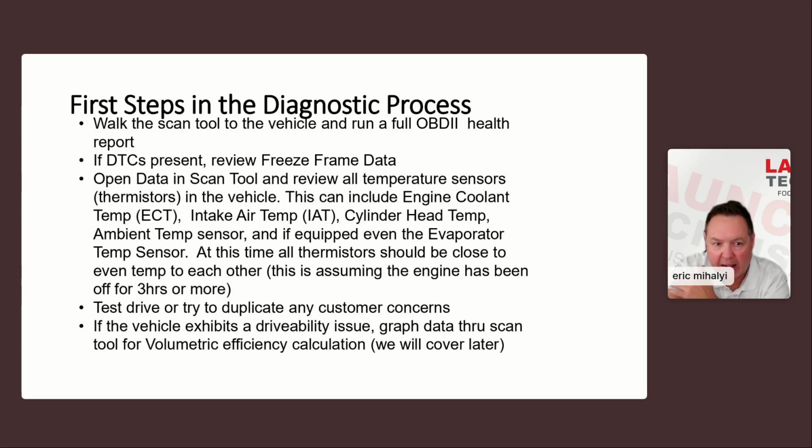So I can't tell you how many cars I fixed with this, or I've found the problems, especially with engine coolant temperature sensors. You can even, on a lot of cars, unplug the engine coolant temperature sensor and watch it go to a different reading. It'll go to a reading that doesn't make any sense, right? Unplug it. Maybe it says it's 91 degrees right now. You unplug it, and all of a sudden it'll go to 190, or in some cases a really low number.